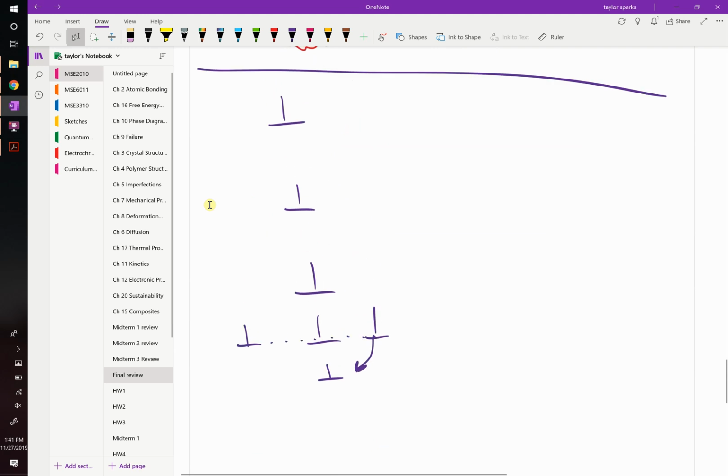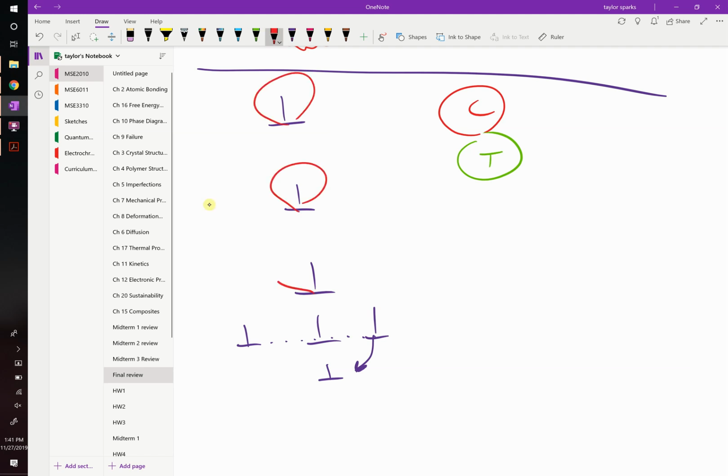Anybody? Strain fields. So think of this vertical line as representing an extra half row of atoms. So let's draw it. We could say that this represents compression, whereas this represents tension. We would say that there is a compressive field, compressive, whereas there's tension here, tension, tension, tension. As much as you can make these red and green overlap, think how great that is. You have compression, which it doesn't like, overlapped with tension, which it doesn't like, but overall, you get a healed lattice there. So of course they're going to stack up.